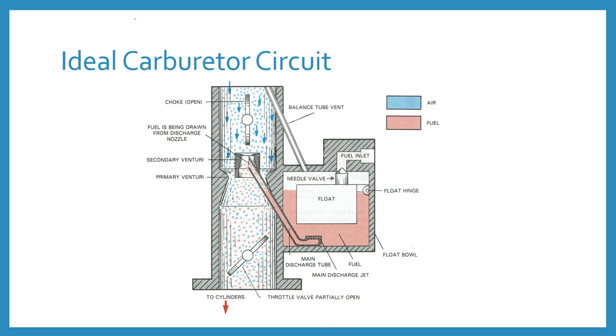Thus, the main circuit cannot be used to supply the fuel. For this reason, the idle circuit is required to supply the air fuel mixture just below the throttle valve, or otherwise the engine would stop.